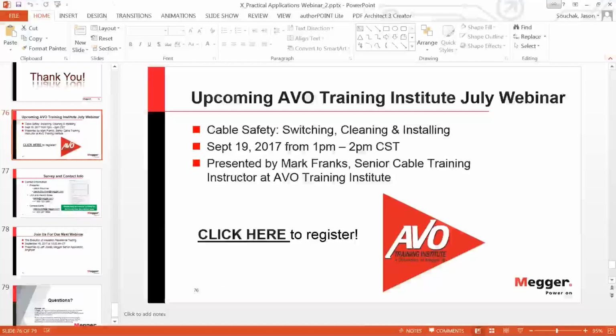Yes, of course we do. Just like with TDRs or anything, transient waves like that, the losses in the cable and the capacitive filter effect, we'll say, of the cable definitely do attenuate out the signals. Generally speaking, it depends on the cable. It's hard to pin a number down, but maybe about 5 miles with a single coupler.